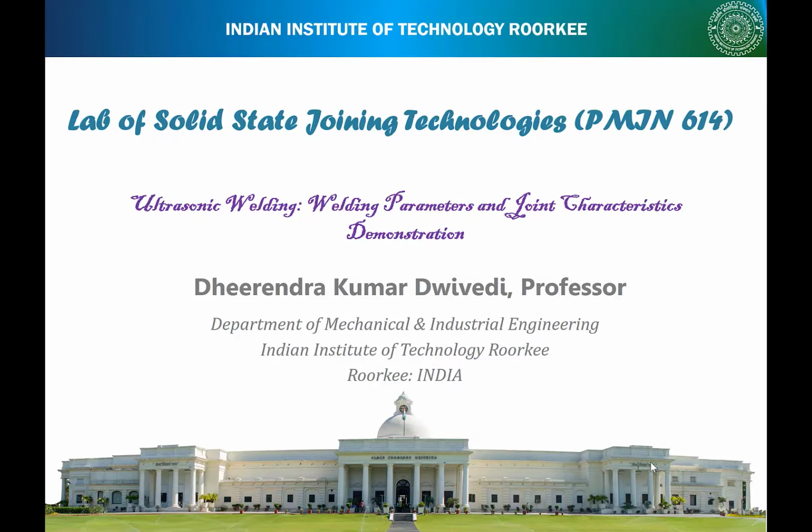Hello. In this lab class related with the subject solid state joining technologies, I'll be talking about ultrasonic welding. This is one of the solid state joining methods which is primarily used for joining thin sheets, thin sections in lap joint configuration using very high frequency mechanical vibrations. So in this practical we will be trying to see the working principle of ultrasonic welding.